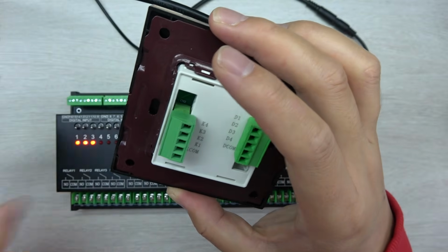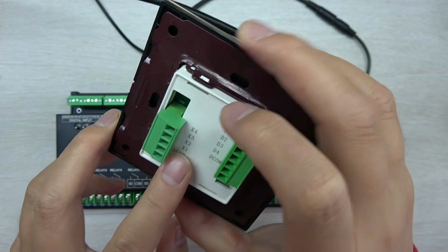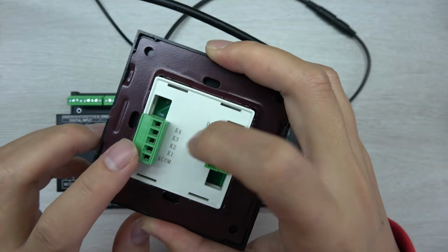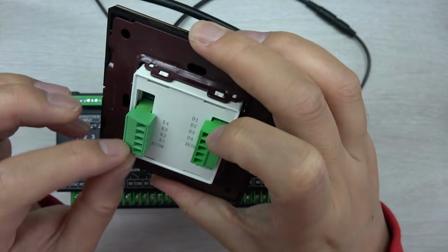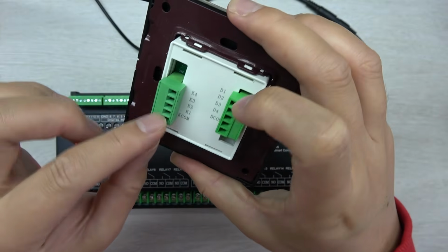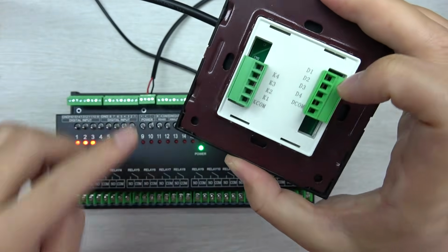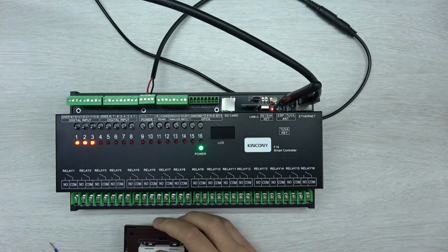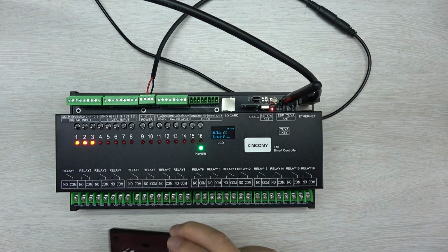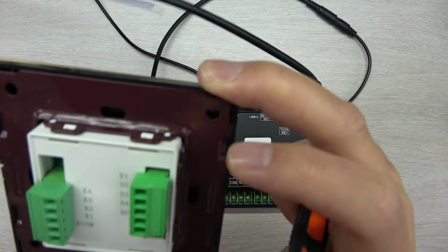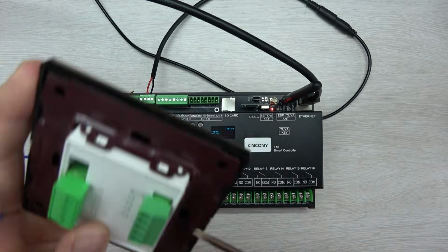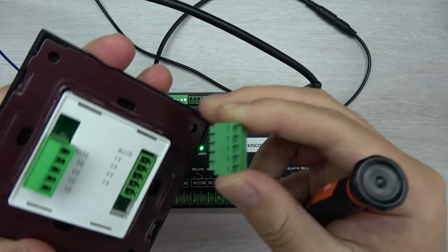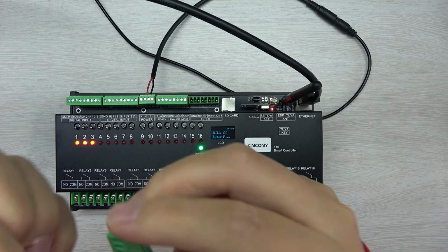If the first lamp, just only one lamp, I just connect with K1. If you have a second switch to control the second lamp, you can also connect with K2. And for the first one, we just do the simplest way. We connect K1 to digital input 1 and the KCOM to ground, okay? So I will use the cable to connect it. And this is removable. You can see this is removable, so you can remove it and connect with the cable.